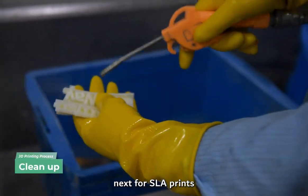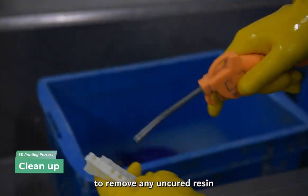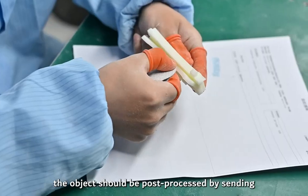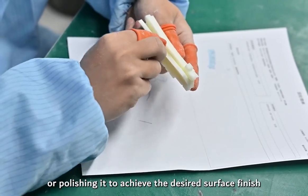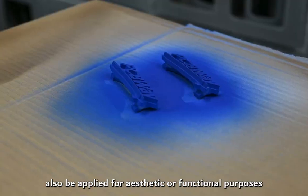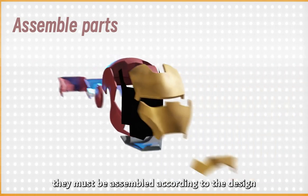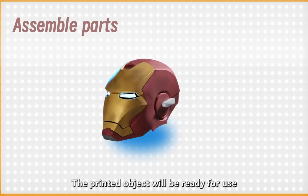Next, for SLA prints, the object should be cleaned using isopropyl alcohol to remove any uncured resin. SLS prints require the removal of excess powder. After cleaning, the surface of the object should be post-processed by sanding, filing, or polishing it to achieve the desired surface finish. Paint or other treatments may also be applied for aesthetic or functional purposes. Finally, if the object consists of multiple parts, they must be assembled according to the design. By following these post-processing steps, the printed object will be ready for use.